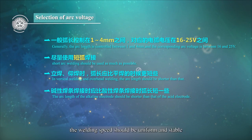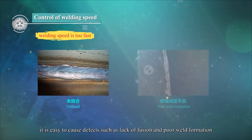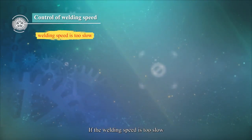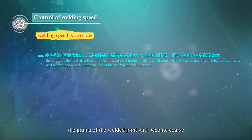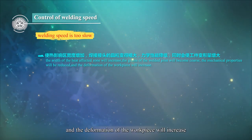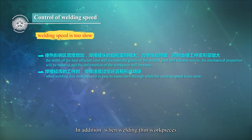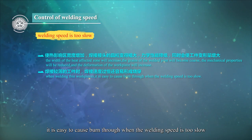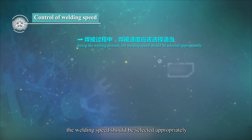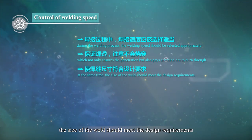During the welding process, the welding speed should be uniform and stable. If the speed is too fast, it is easy to cause defects such as lack of fusion and poor weld formation. If too slow, the width of the heat affected zone will increase, the grains of the welding joint will become coarse, the mechanical properties will be reduced, and the deformation of the workpiece will increase. In addition, when welding thin workpieces, it is easy to cause burn through if the welding speed is too slow. Therefore, during the welding process, the welding speed should be selected appropriately to ensure penetration, no burn through, and the weld size as required.